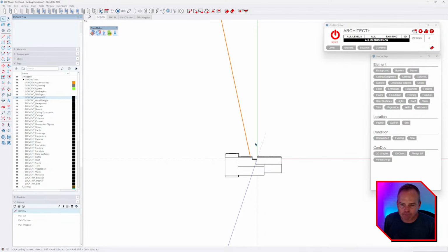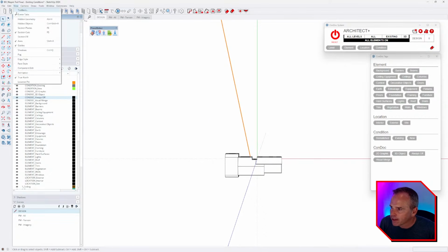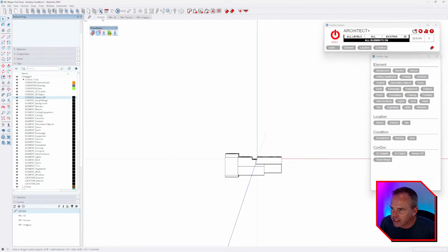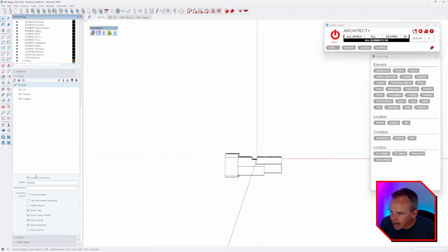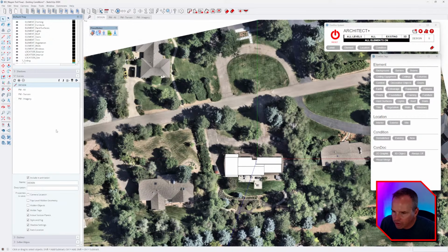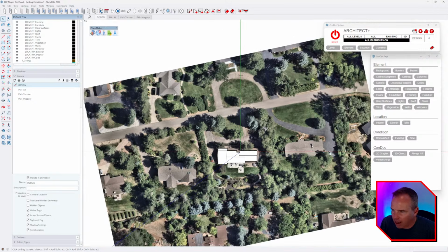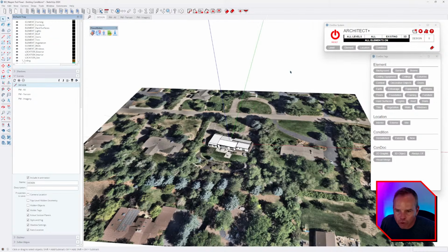All right, so I've messed around with my axes, right? So now I'm going to turn that off, and then I just need to go to my scenes dialog, and my design scene, I want it to hold on to the axes location. And when I check that on, that should grab what I had. So now if I were to right click and hit reset, that's the origin. So every SketchUp model has the absolute 000 and north and all this, and that's the origin.